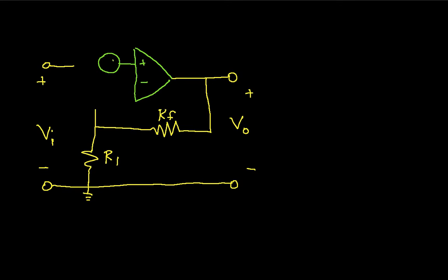And we have the input referred noise source connected to the non-inverting input, and the inverting input is connected to the resistors. Okay, and we'll call this Vn. And we talked in the last video about how to get Vn, which is a function of the op-amp as well as the system bandwidth. So we talked about how to get Vn from the op-amp spec and the system bandwidth.